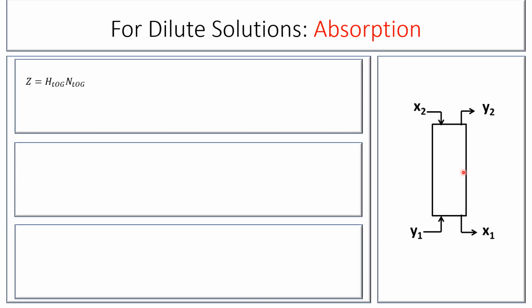You can consider these sections to be similar to the number of stages we used to calculate in chapter 3, and also you can think of them like those in a tray tower, where each tray is basically a stage by itself. Now they are theoretical because we know that we have continuous contact between the gas stream and the liquid stream in a packed bed. We don't have separations after each section. But they are going to be very helpful in calculating the height of the packed column.